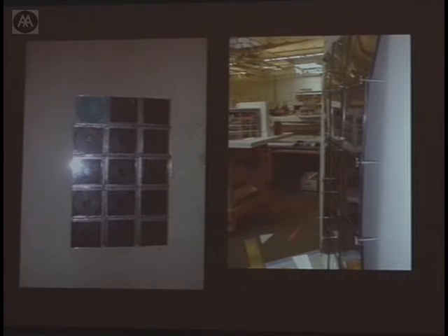So I raided my wife's CD collection, and she makes film, so I stole her gaffer tape and wove this stuff together. We put it onto pins, and you find that as you move this stuff around, you can actually achieve double curved surfaces. The point is that the slack is taken up in these gaskets. It's very much like a concertina between train carriages. The train carriage is a straight thing, and the concertina takes up the slack. So everything is about that little concertina joint. How much distortion can there be? How much warping can there be before I have waterlogging, or the fabricator says, if you do that more than 3 degrees, I'm not going to guarantee that it's going to age properly, and your rubber might break away.